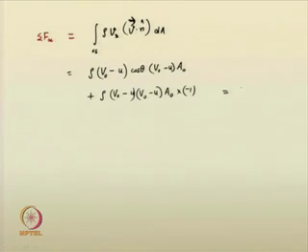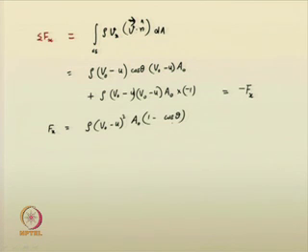So, it will be minus f x, because we have suggested f x in the other direction, if you recall. So, f x can now be written as rho into V 0 minus u square A 0 into 1 minus cos theta. Fine. So, this is the x component of the force.